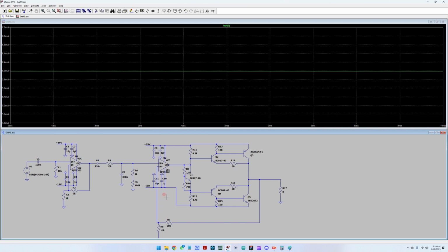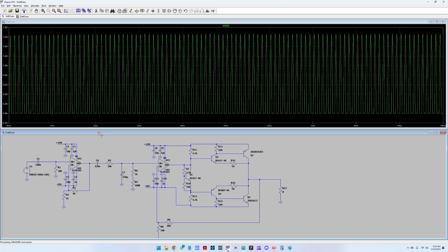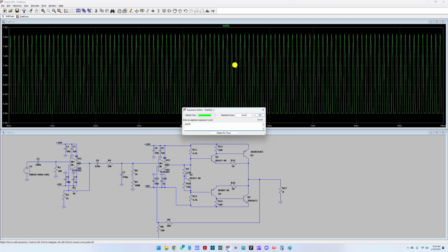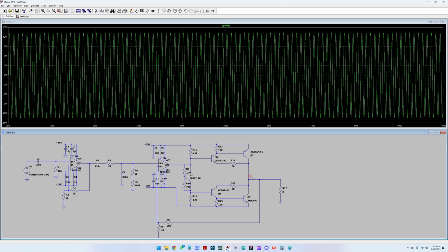Okay, let us see. Now we're seeing a current, so we're just measuring. Yeah, this is only the high side. I was wondering why everything gets cut here, but this is only the high side. So let us remove this trace here and connect the output, and it's a beautiful sine wave at 13 volts.